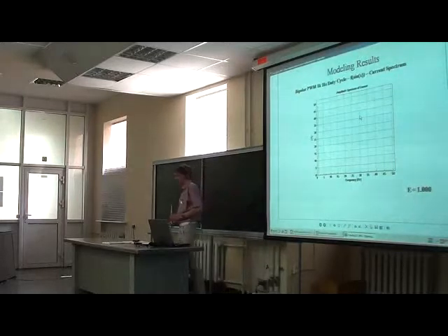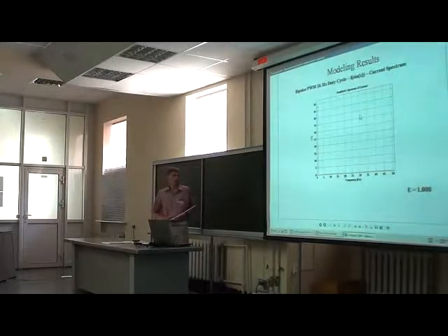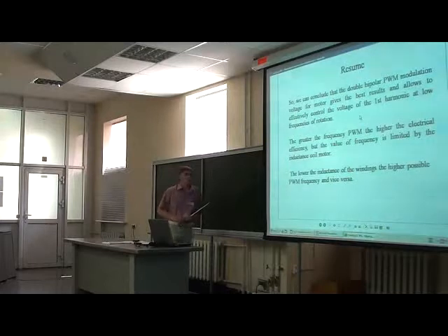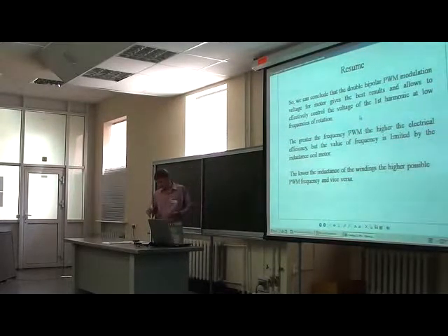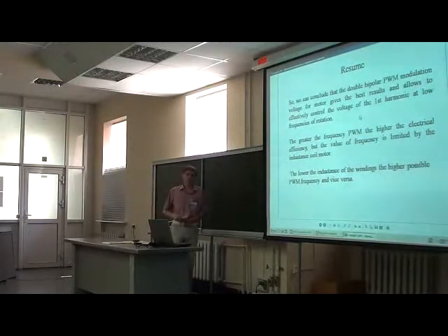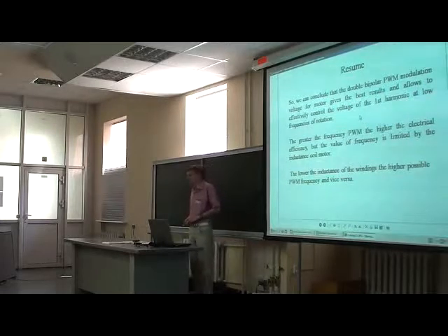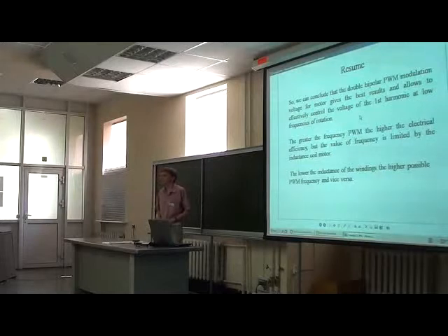it's limited by the inductance of the windings of the motor. The low inductance of windings allows high frequencies of PWM. And from this simulation and modeling we can choose the right way to control the BLDC motor for such an application as Sphero robots, except at low and ultra low speeds of rotation. That's all. Thank you for your attention.